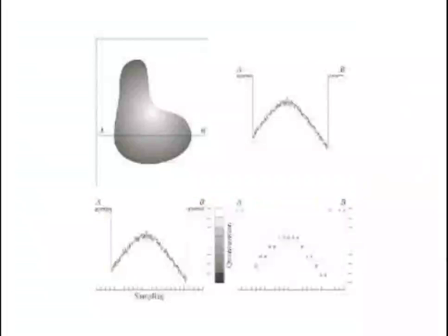However, the values of the samples still span, that is vertically, a continuous range of intensity values. In order to form the digital function, the intensity values also must be converted, that is quantized, into discrete quantities. The right side of figure C shows the intensity scale divided into 8 discrete intervals ranging from black to white.